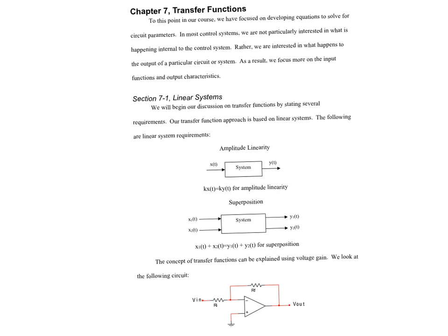So we'll do things as transfer functions, which is where we came up with the term transfer function: all we're doing is we're transferring the input to the output. Whatever is in the block is going to transfer whatever input signal you have. It could be a current, it could be a voltage, it could be a tank level, it could be a line flow, it could be a position. I mean, there's just about anything that you can come up with a system for, and you can output that to whatever other one is.